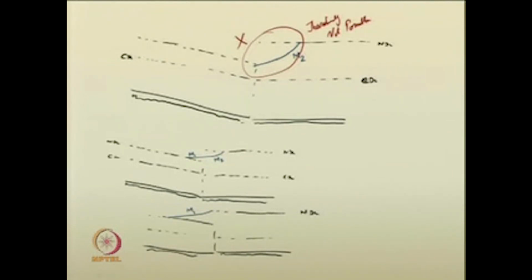Again in this case, the M1 is theoretically possible, but as soon as from this center line to here in channel 2, the curve is M2, it is in zone 2 and it is positive. So, that is also theoretically not possible.